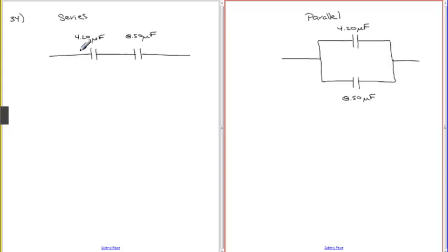And the key thing to remember about series capacitors is that the charge is the common thread. So if one capacitor plate has a plus charge, the other plate has to have a minus charge, and the corresponding capacitor that's in series has to match up, because the electrons that are on this plate go over to this plate to make this one negatively charged and make this one positively charged. So they have to balance up. There's no current that flows between these capacitor plates. So any electrons on this side are just redistributed from one plate to another.